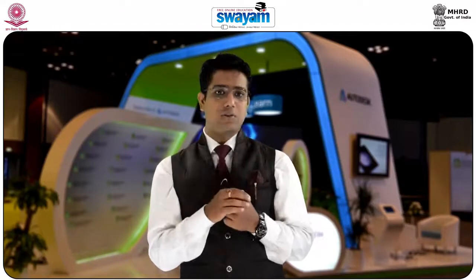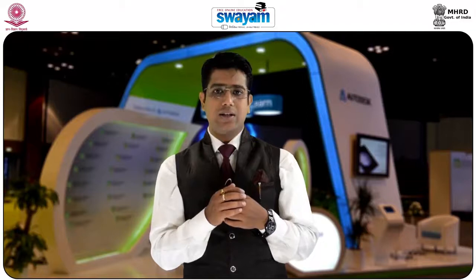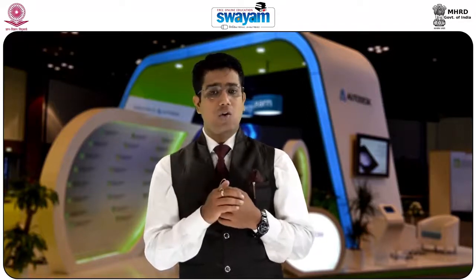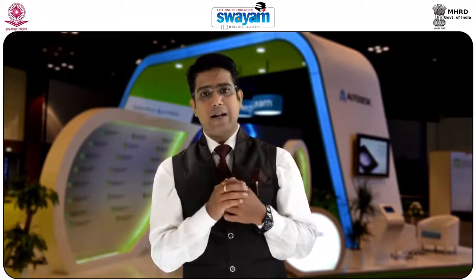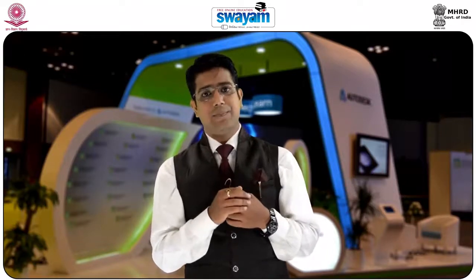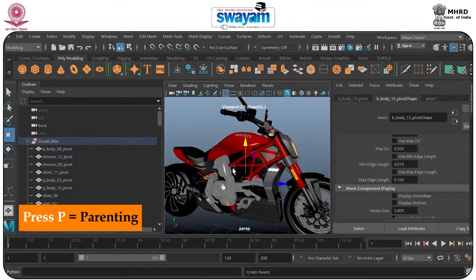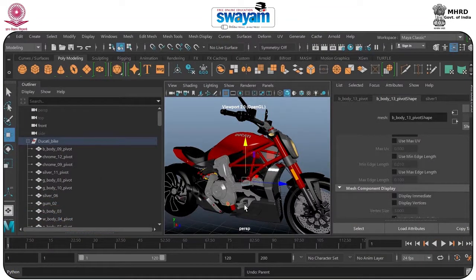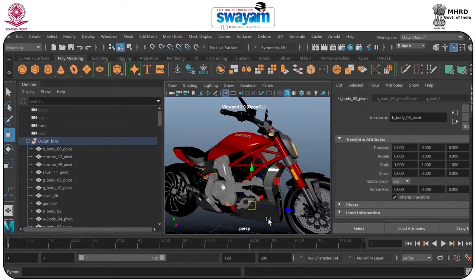with that object also. There are two basic ways to connect multiple objects together in grouping and parenting. First, you can use the P button, or you can go to the Edit option and Parent. Parent two objects together by selecting the child and then the parent, and hit P to get parenting. So when a parent moves, the rotation and scale also move the child object. However, you can still move the child object independently of its parent.